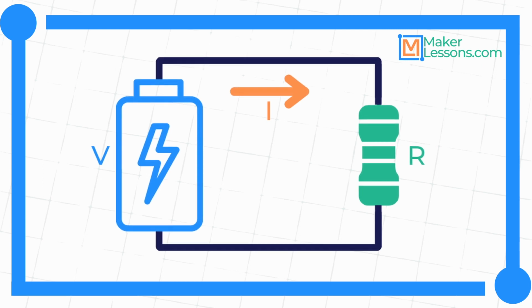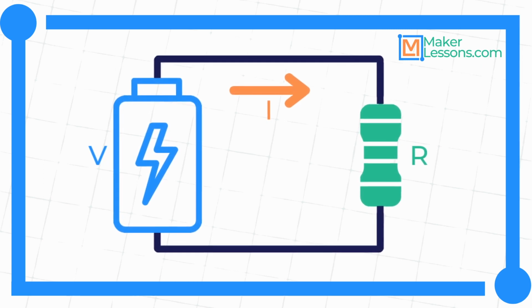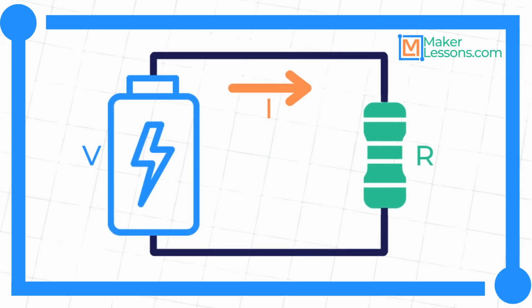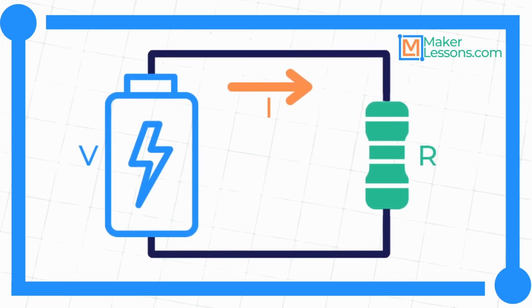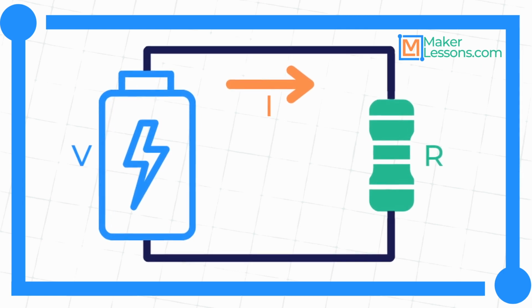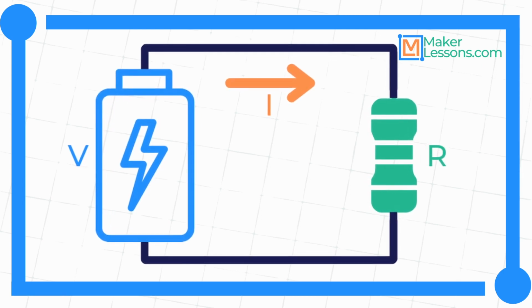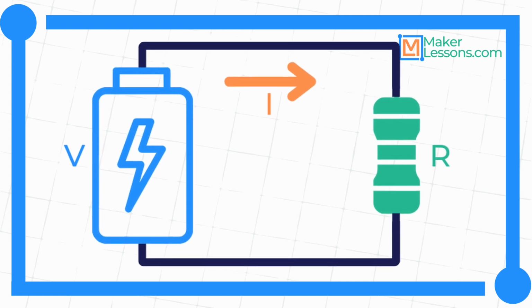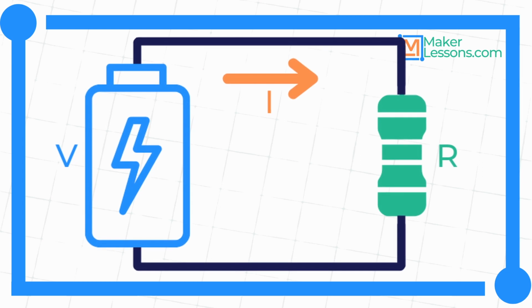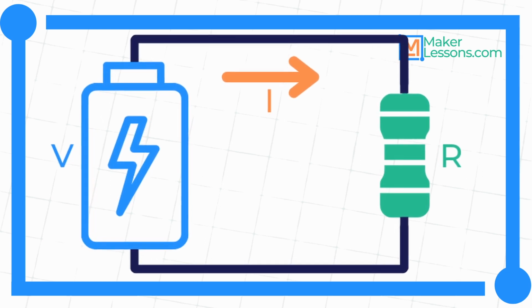When analyzing electrical circuits, the actual direction of current through a specific circuit is usually unknown until the analysis is complete. Consequently, the reference direction of currents are often assigned arbitrarily, usually following conventional current flow. When the circuit is solved, a negative value for the current implies the actual direction of current through the circuit is opposite of the chosen reference direction.